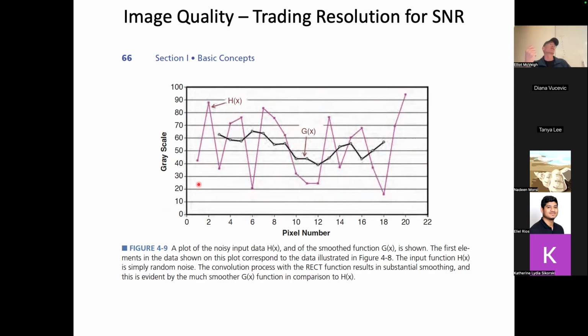When you look at the signal that is coming out of that antenna, if you take it away from the patient and you look on your oscilloscope, you'll have some random noise. So that antenna is basically like a resistor. And so it has Johnson thermal noise, it's called, like molecules are jiggling around inside that thing, and they will just create a tiny voltage, even though there's no signal on the antenna.